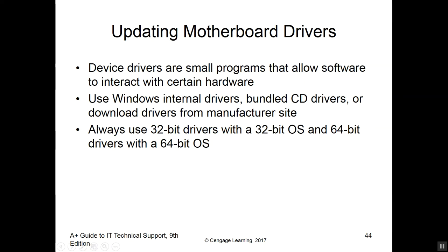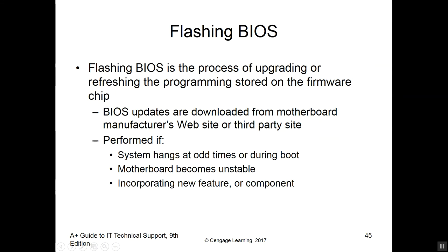If we make a change that alters the ability of this motherboard to function, we could have taken out the system, and sometimes it's cumbersome repairing an issue in the BIOS if we've done a bad flash on it. Now, we've got 32-bit drivers that work with a 32-bit OS, and 64-bit drivers work with a 64-bit OS. It depends on the motherboard and the OS, and everything's got to be compatible.